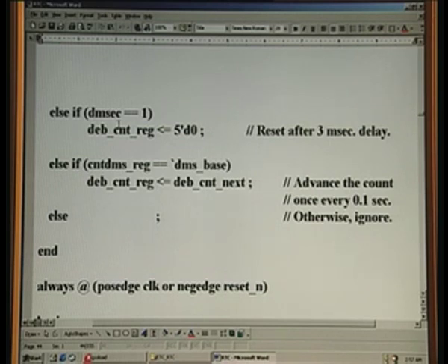And every time the clock strikes, which if it is 20 megahertz will be every 50 nanosecond, this is going to take place. Although we have seen several always blocks, it implies that they are all parallel circuits. It is not a sequential circuit, as I have been impressing time and again.